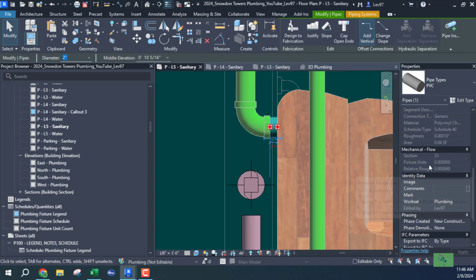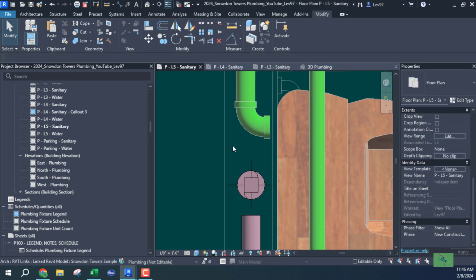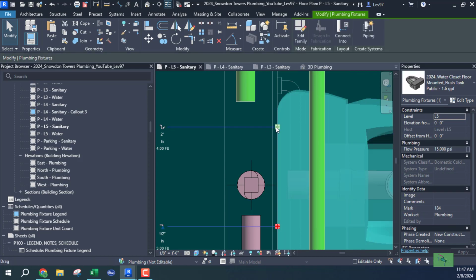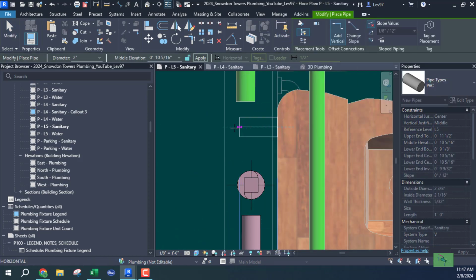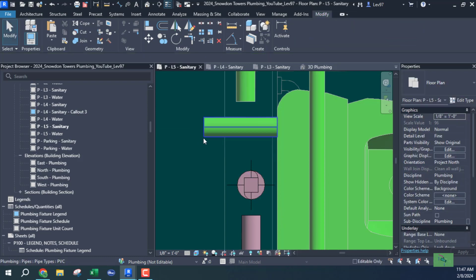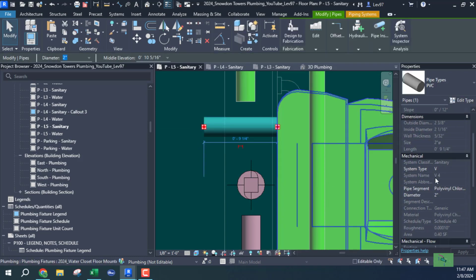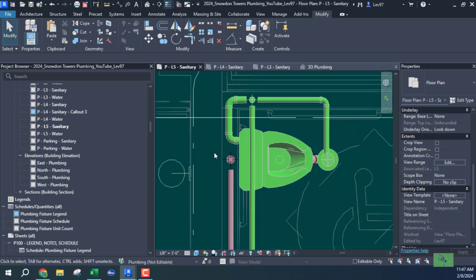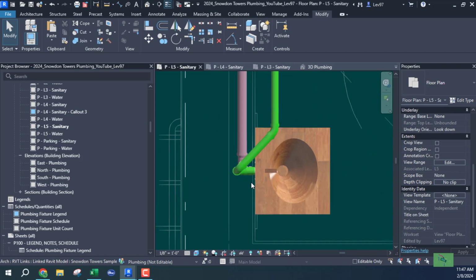Let's make sure that when you cut and paste your piping, the fixture units don't carry over, so you have to redo them. Which is not a big deal. I mean, I'm still thinking whether or not this was more efficient than laying out the piping. Vent, okay, we have vent, and we should have some plumbing fixture units. Fixture units is 4. That's okay. Okay, we still have that, and the same with.